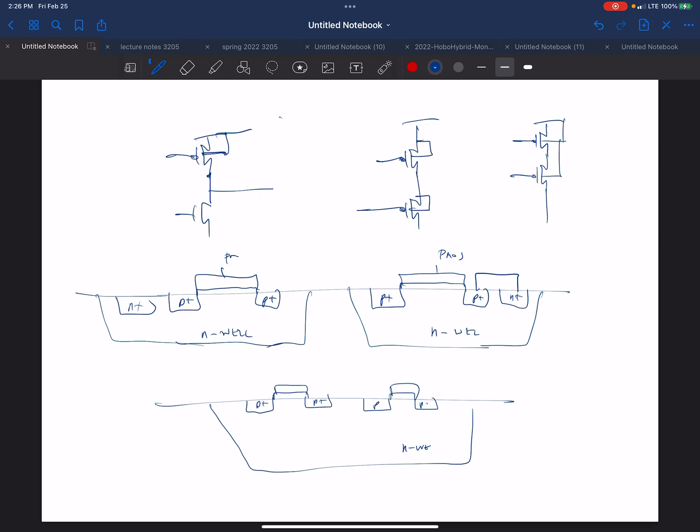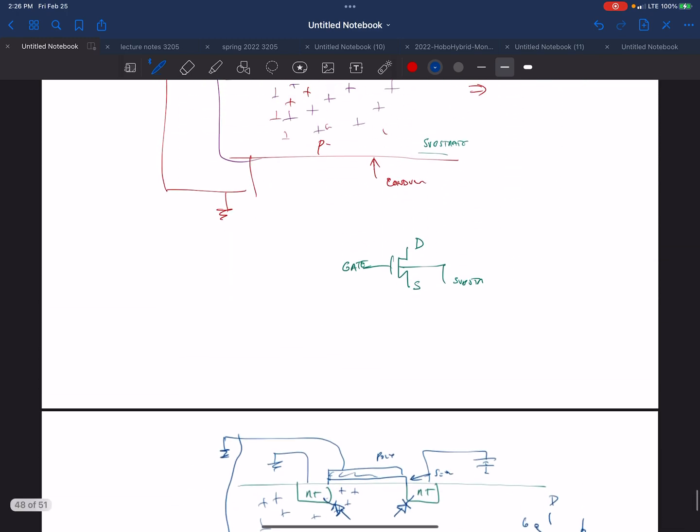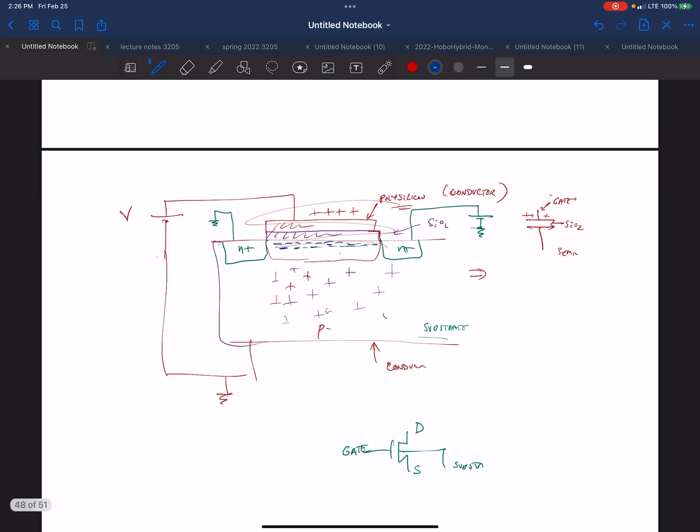In the scenarios that I showed you guys, I'm controlling this transistor only with the gate voltage because my substrate's at a known voltage. It's either grounded in the case of NMOS, or goes to VDD in the case of PMOS. So I just have this gate connection. So I've got this switch model, right? Whatever the gate does, I can turn on and off this transistor.